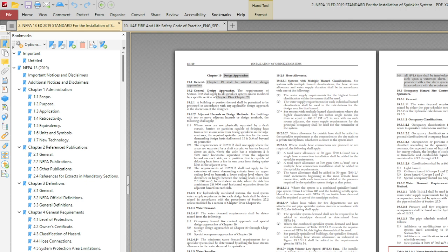So what is the flow? Assume that it is 1000 GPM. For example, I will explain to you how we calculate 1000 GPM, but as of now, 1000 GPM is the calculation. What you calculated, multiplied by 60 minutes. So it will give you gallon per minute multiplied by minutes. Minutes will cancel, and you will get total gallon. So that will give you your water tank calculation.